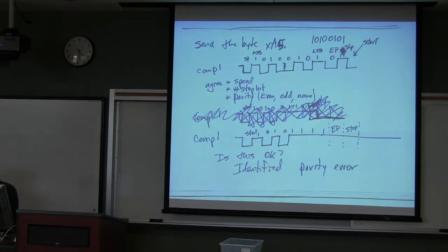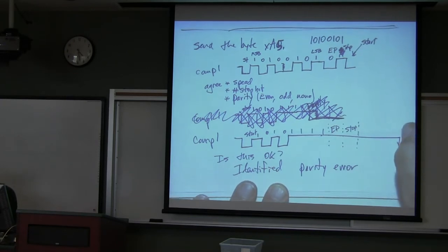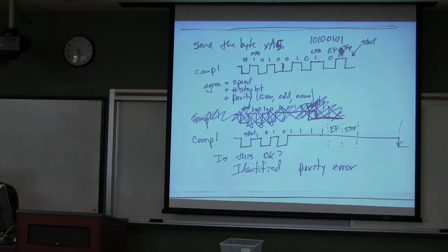And by the way, this is pretty typical. If you have a communications fault, it's usually not a single bit thrown here and there. It's usually a whole bunch of stuff. The other thing pointed out here is that there's no start bit, right? So when this finally goes down, that's when it would first say, oh, here's the next thing being communicated.